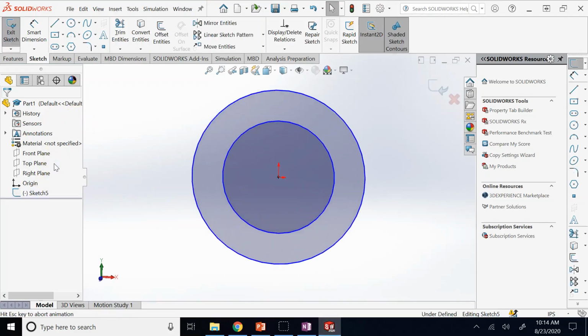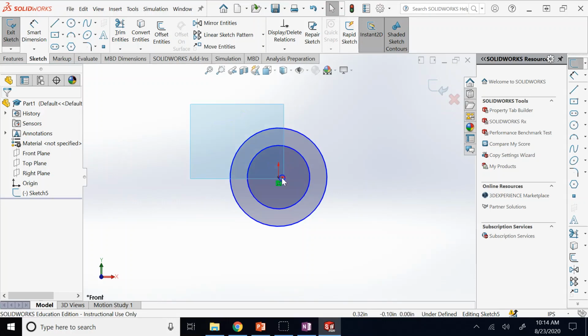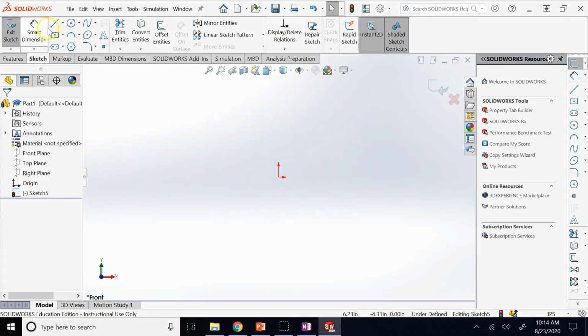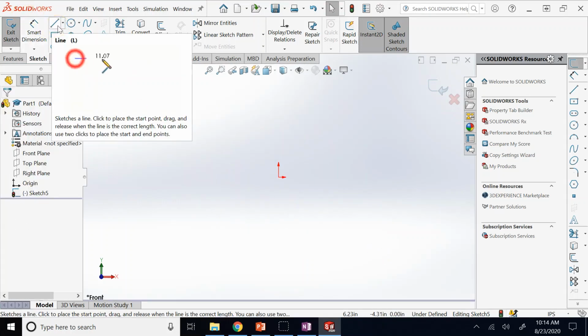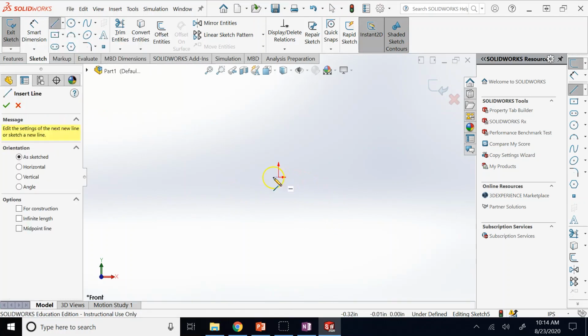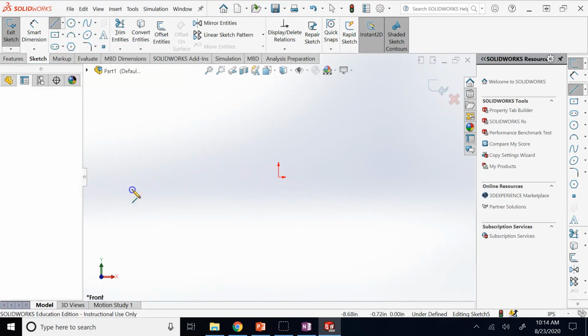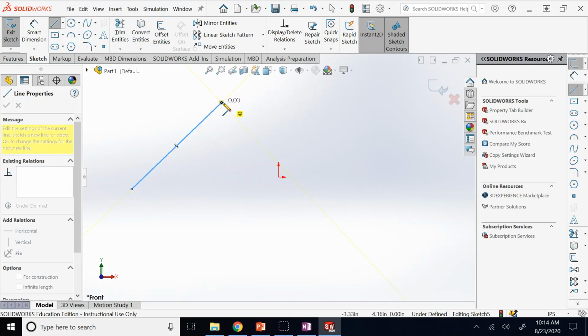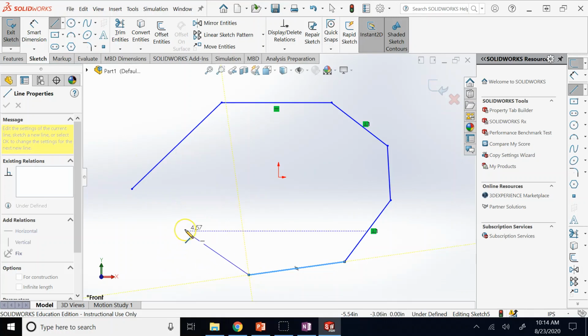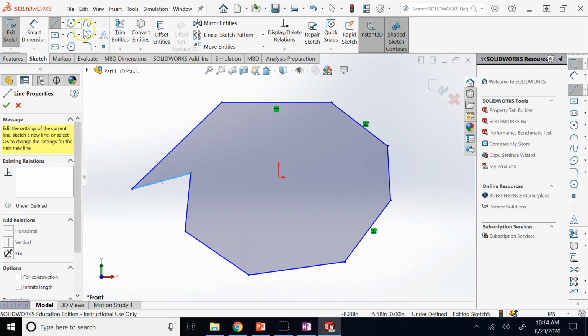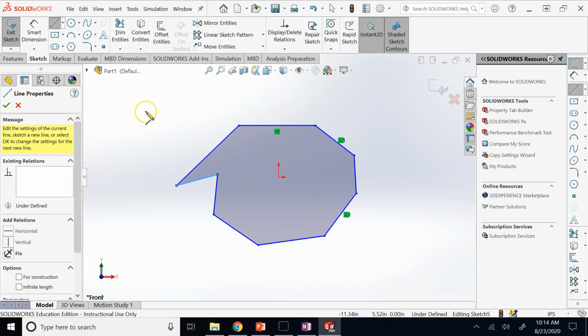So here, as you can imagine, starting from here, line is quite obvious. You just click and then draw a line from any point to another point, right? And then this command does not turn off, so you can keep drawing lines that are connected to the previous one, right? So you can draw a profile. Well, that's what we call in CATIA a profile. And then you can keep drawing, and if you want, you can close the profile. If you close it, then still it's on.